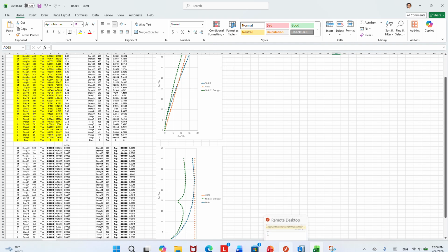Yeah. So for the drift, you said it's the height over 350. Yeah. On the wall, okay. Criteria is H over 350. 1 divided by 350 is the slenderness ratio. Okay. So this is a diaphragm story drift.